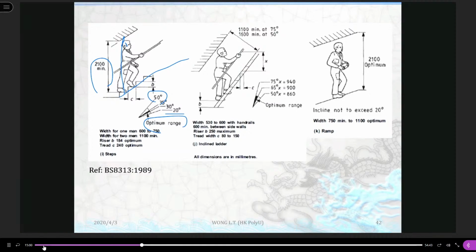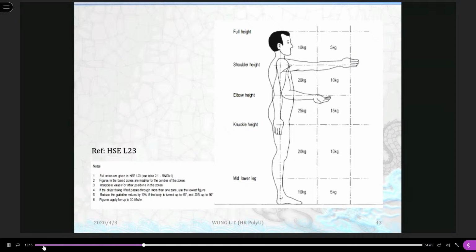So in here, from this British standard example, we do have some idea when planning the classroom access and also the surface space required. Actually, those dimensions also relate to basic ergonomics data, and this ergonomics data includes the dimensions, also the physical strength. Say a staff member is required to conduct some maintenance work, to lift something or detach something using a hand tool. The strength expected for a normal staff member can be assigned in there.